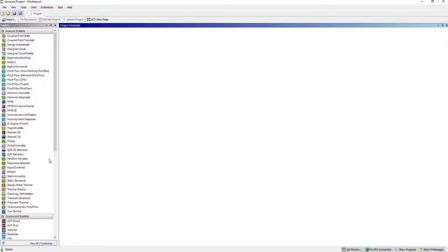Hello everyone. So this tutorial is about how to do a simple fluidized bed problem. What we are going to do is use a Eulerian granular model to simulate a fluidized bed problem, and this is going to be a Eulerian simulation. What I mean by that is both the fluid phase and the particle phase are going to be solved as a continuum phase.